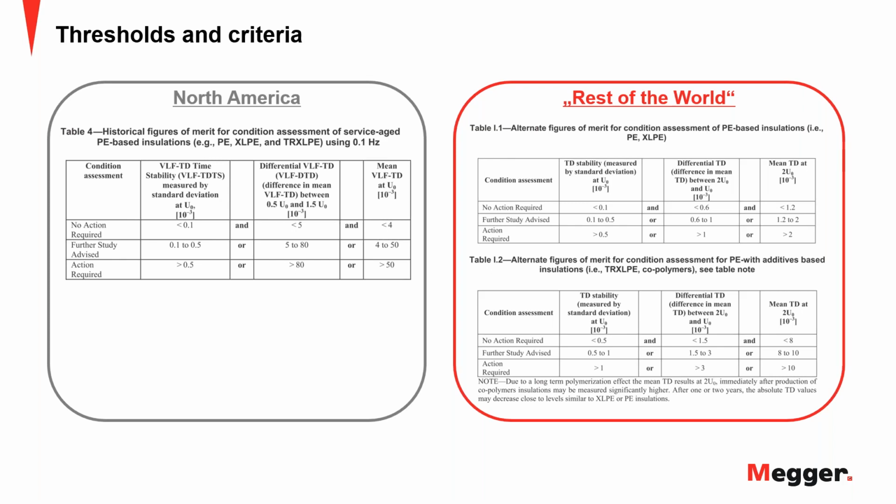So you certainly can find out those differences when you do the leakage current test per phase and you do the tan delta per phase. Then you will see the differences.